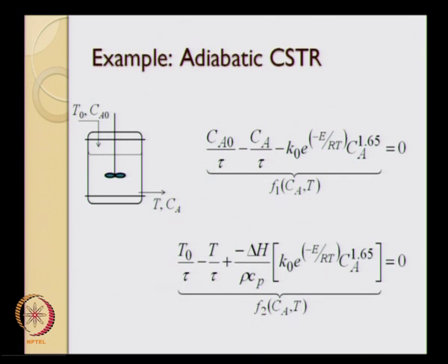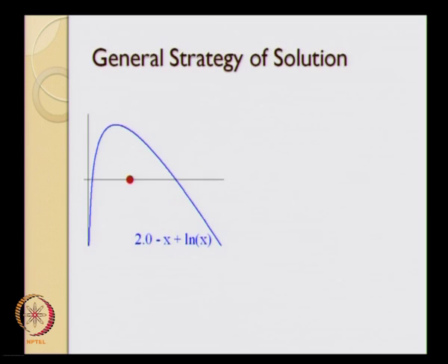We will have the mass fraction of component A in the liquid, the mass fraction of component A in the gas phase, and temperature. These are the 3 variables at each of those stages, so we will end up with 3 multiplied by 40, which is 120 variables. So we might actually end up with 120 equations and 120 unknowns, and that would be an example of a multidimensional system of nonlinear equations.